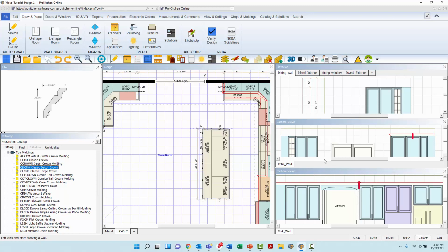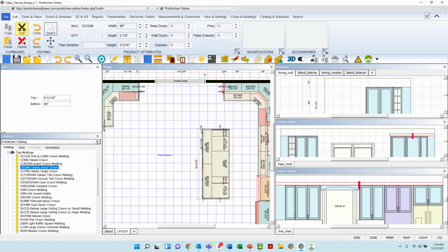To delete a molding manually, hover over the installed molding and right-click the mouse to open the menu of items. Hover to the nomenclature of the molding, then into the toolbox and select Delete. Or, left-click the molding and either left-click the Delete icon in the Edit ribbon or tap the Delete key on the keyboard.